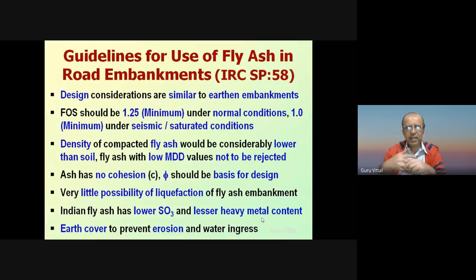Actually, what is liquefaction? Liquefaction is when a fill material loses its entire shear strength and behaves like a liquid. Liquefaction usually occurs when there is an earthquake. When there is an earthquake, vibrations and earthquake forces are there. So soil material which is in a loose state and which is saturated, having water in its voids, liquefies.